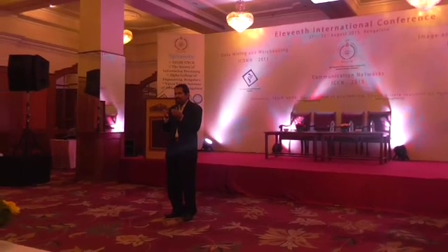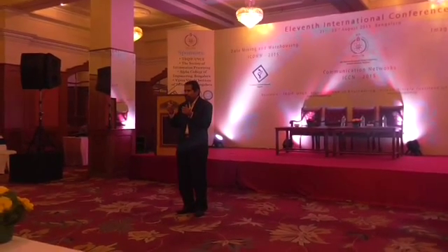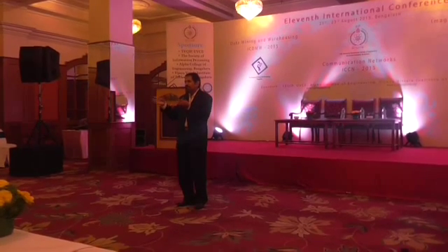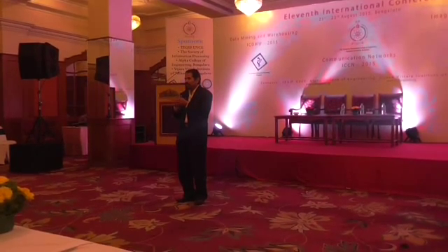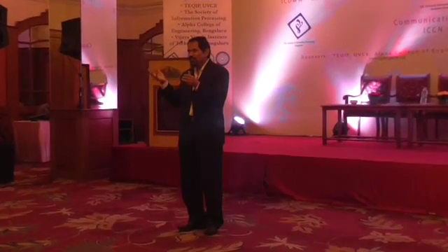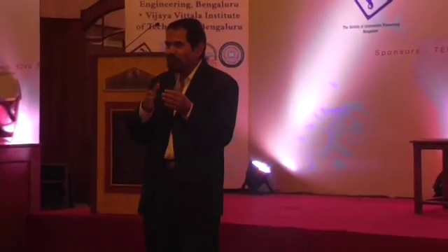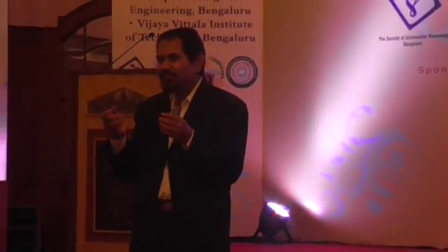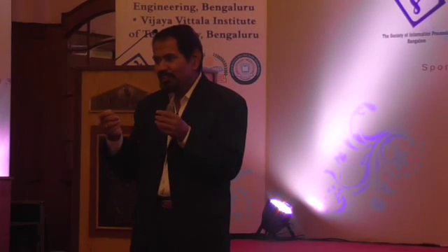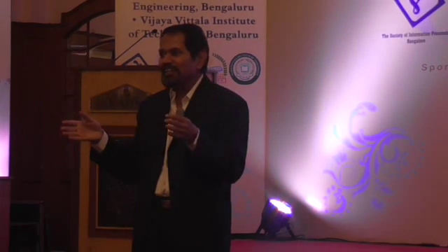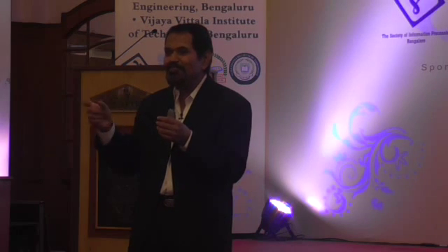For data like a static picture of not high resolution, you may need some 100 subcarriers. But if you want to transmit full motion video, of very high quality like 4K TV, you would like to use 1000 subcarriers. Depending upon the requirement, dynamically, you can use as many subcarriers as you want, and you have the flexibility of doing that.